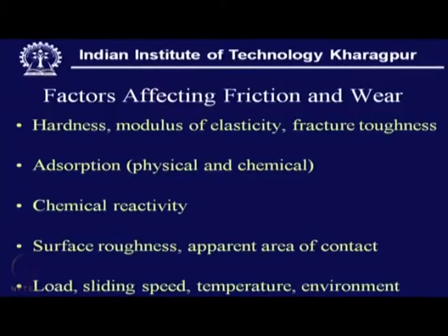Now, when it is two bodies in contact, it is also adsorption of that surface, the tendency to get adsorbed, and it can be a physical or a chemical phenomenon, and that may greatly affect this particular friction and wear. Now, chemical reactivity: adhesion to that particular surface and having a chemical reaction, making a bond formation,